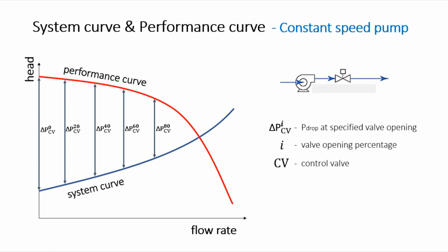This can also be shown as this new illustration of new system curves for each flow rate. And it is clear that by installing a throttling valve, we create additional losses, which is the wasting of energy, and this can be considered an inefficient option.